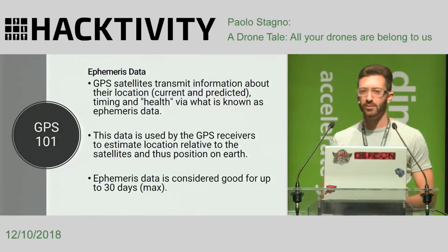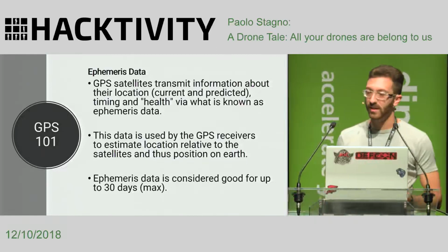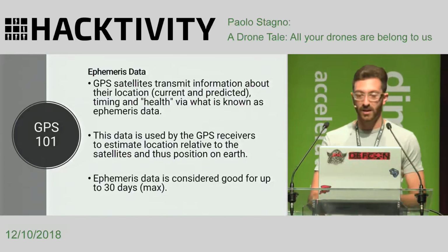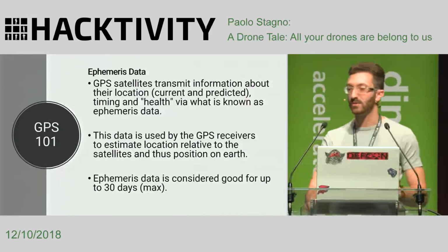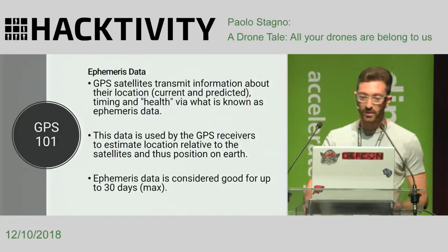The first time that I tried to perform GPS attack, I was using a really old ephemeris data, and I wasn't able to spoof GPS signals. So I would recommend, if you have to try, to download the last ephemeris data, because I lost the entire morning trying to understand why it wasn't working.